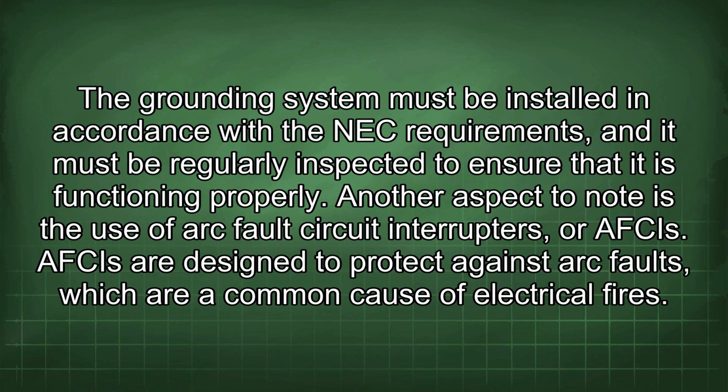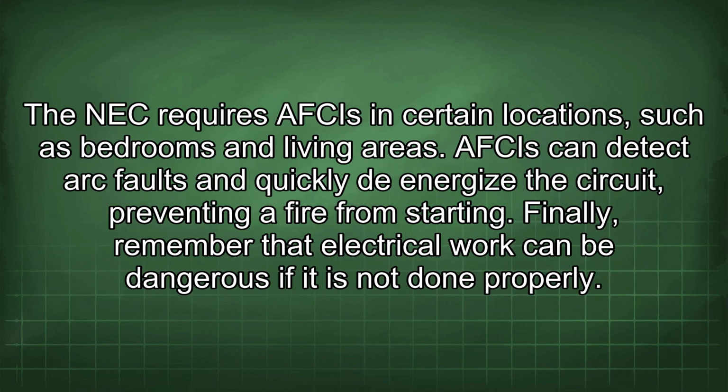Another aspect to note is the use of arc fault circuit interrupters, or AFCIs. AFCIs are designed to protect against arc faults, which are a common cause of electrical fires. The NEC requires AFCIs in certain locations, such as bedrooms and living areas. AFCIs can detect arc faults and quickly de-energize the circuit, preventing a fire from starting.